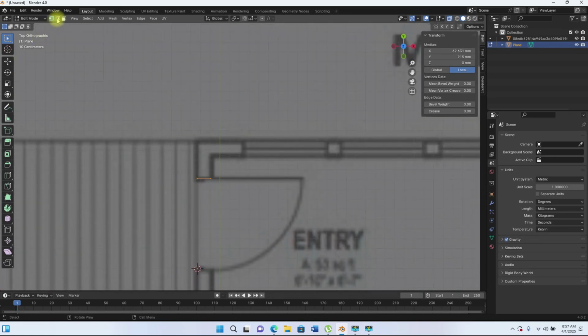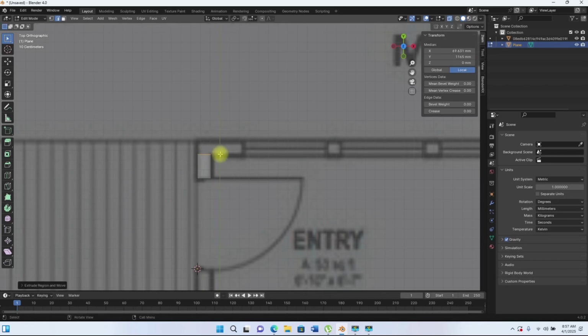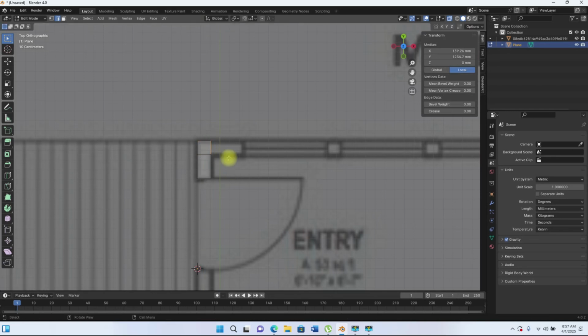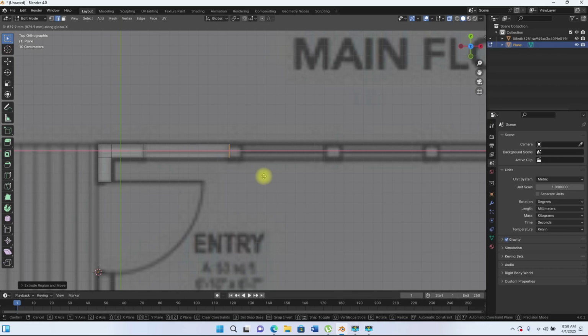So we'll go back to edge, select that edge, E for extrusion, constrain it to Y so that we can go up. We'll click. Every time I have a transition, I'm going to extrude there. So EY again, extrude all the way there, select this edge. This time I'm coming horizontally. You can see from this axis horizontal is X. So let's quickly do that. EX, extrude to this point. EX, extrude to this point. We do not need this, but we just do this because we want to know where all the panels are.